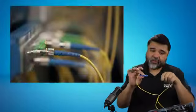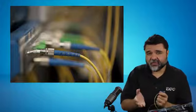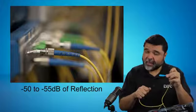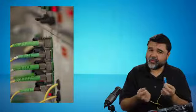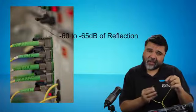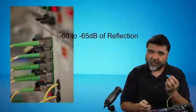So if I were to take two blue UPC connectors and mate them together, I would expect about minus 50 to minus 55 dB of reflection. If I had an APC connector mated to another APC connector, I would expect about minus 60 to minus 65. So APC connectors have less reflection. So they are a higher performing connector in that regard.